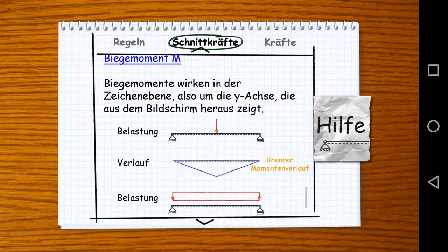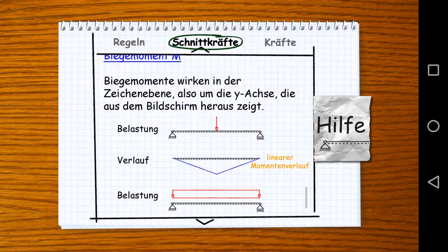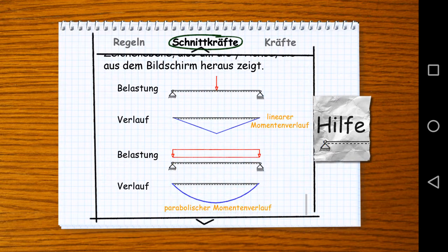And the last internal forces we need to think about here are bending moments. So what happens with bending moments? Let's say the easiest way to draw bending moments is just to imagine how your beam is going to deform. So what's going to be the deflection curve? And when you can picture the deflection curve, you can easily know on which side the moment is going to be, depending on where the tension is. So I'm going to try to explain it.